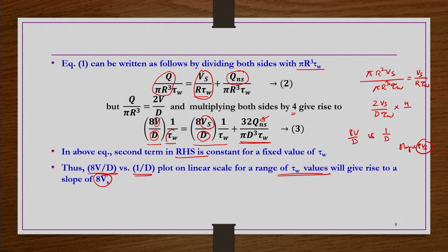So, you may be thinking why tau w, because it may be cancelled out. No, because what we wanted is a relation for different shear stress. After incorporating all other corrections, such as end effects etc., the shear stress is the true shear stress, that is reliable. So, whatever shear stress we get is reliable. That is the reason for different values of shear stress we are trying to do this, so that we get some value for the velocity slip.